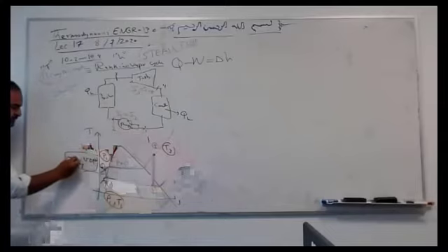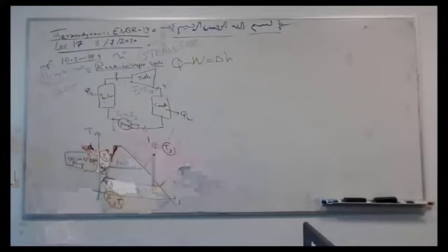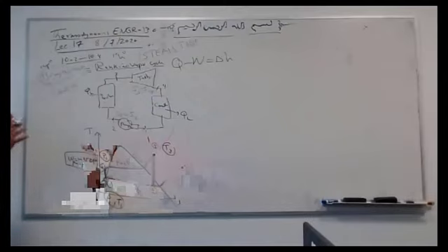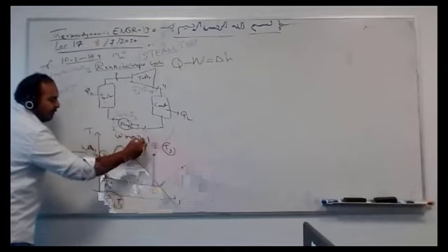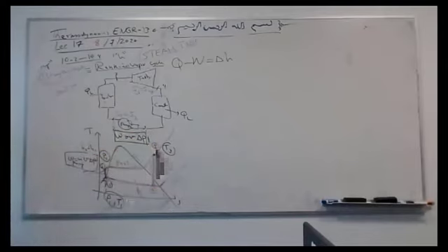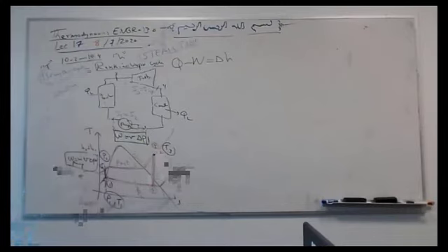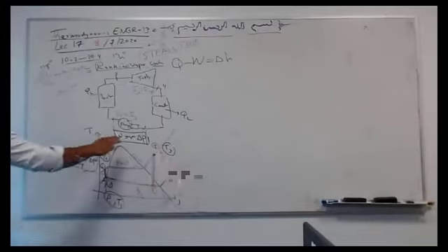If it had a mass flow rate, m dot VdP. Why VdP? Because the volume is constant. Do you remember when I said if you have an open system, steady, reversible, and I compress at constant volume, like a pump, I can say W equals VdP? Where does it come from? Does anyone remember this sentence? When you have an open system, steady, reversible, the work is always PdV, but if it's open system, steady, reversible, I can say VdP.